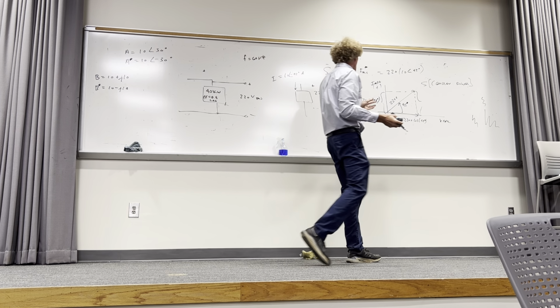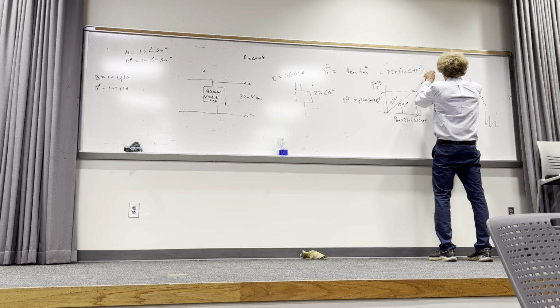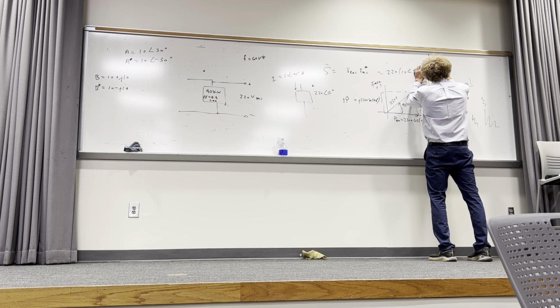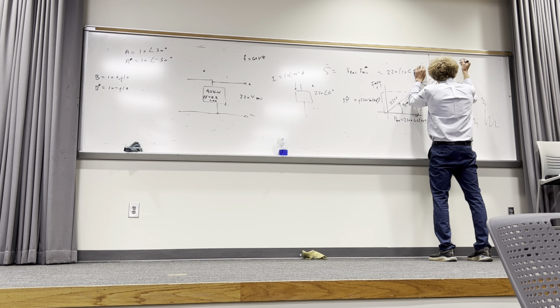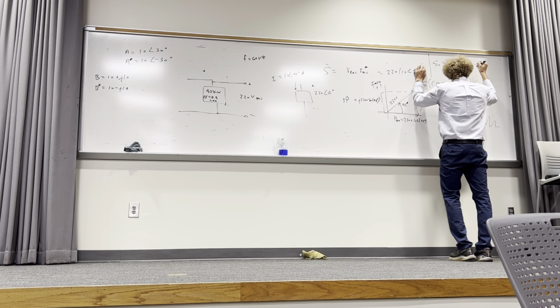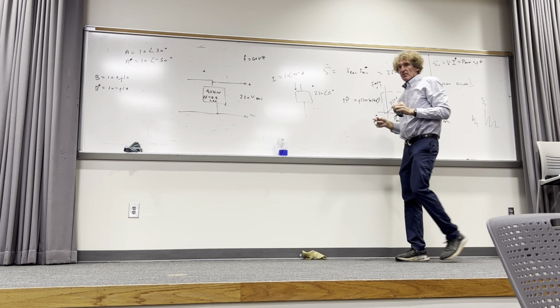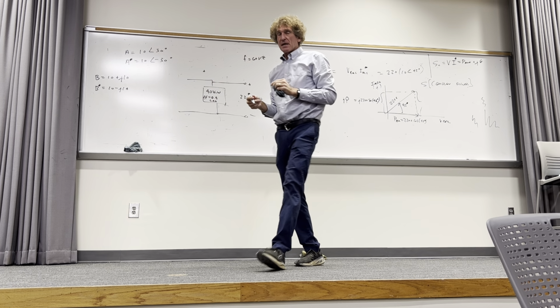So when you talk about complex power in general, I'm going to put it up here. In general, S, the complex power, is going to be V, whatever the voltage is, with its magnitude and angle, times whatever the current is through that element, conjugated. The real part is the average power that you've learned about, and the imaginary part is JQ, the reactive power. Get the idea?